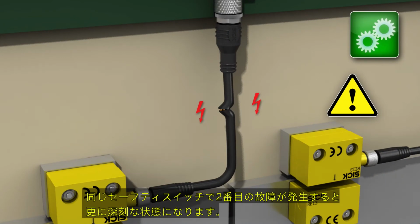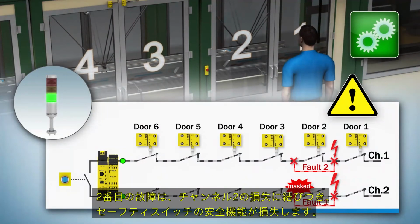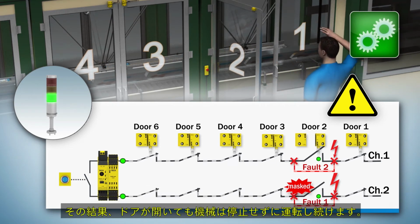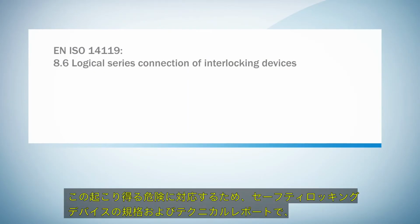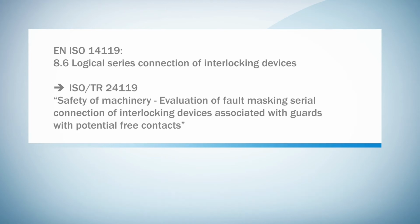As the cable was already damaged before, the second fault is even more probable. The second fault would lead to the loss of the second channel and therefore to the loss of safety function. The machine will then keep on running even if the door is opened. Because of this possible danger, the standard for interlocking devices and the technical report limit the performance level of cascaded safety switches with volt-free contacts.